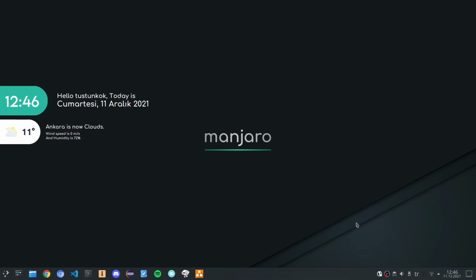First, we need a simulator and a compiler to compile our VHDL codes. In the lab, we have a Windows XP machine with Xilinx Vivado installed, but my working environment is a Linux-based Manjaro system. Because of that, I'm going to stick with open source alternatives. I'm going to use an editor called Visual Studio Code, and for the compiler, I'm going to use an open source one whose name is GHDL. GHDL has a very good user guide that you can always consult, and the working principle is very similar to Vivado.